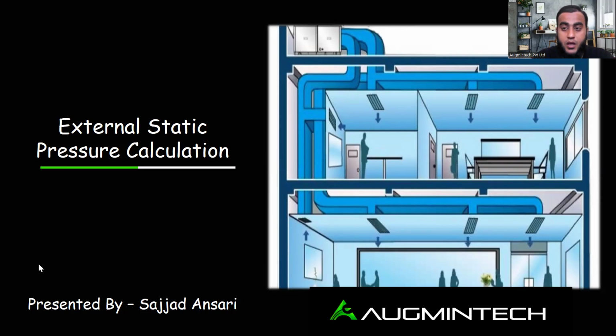But remember, we need to submit the total static pressure. Total static pressure means internal static pressure plus external static pressure. The internal static pressure value you will get from the manufacturer side, the HVAC unit manufacturer. They will give you the internal static pressure. What is internal static pressure? Don't worry, I will explain each and everything. Second, as an HVAC designer, our main target is to calculate the external static pressure. As per this, you will get the fan capacity. That I will explain.